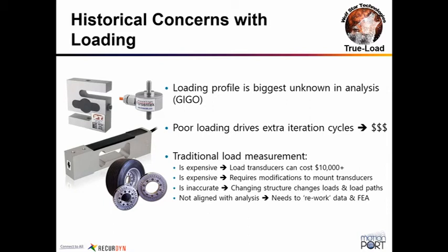But to be able to measure loads directly with load transducers, these things can be very expensive, and as you can see, kind of bulky. In some cases, this instrumentation is big enough that it actually throws off the loads in the component. In other words, if the instrumentation is significantly large compared to the component, then the measuring itself is throwing off what's really happening.